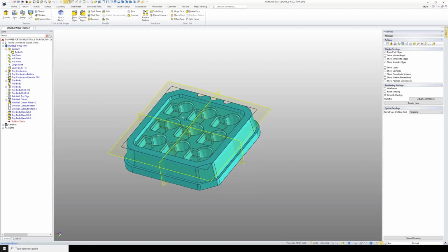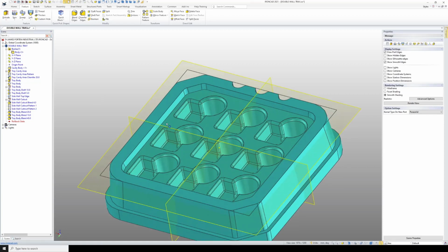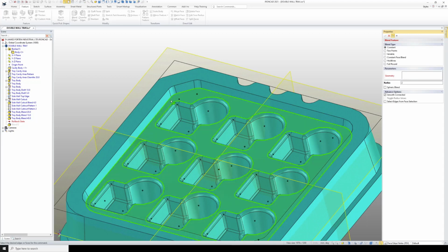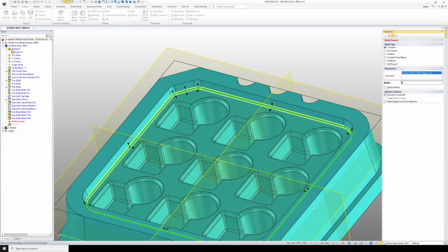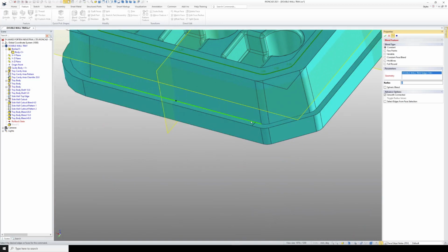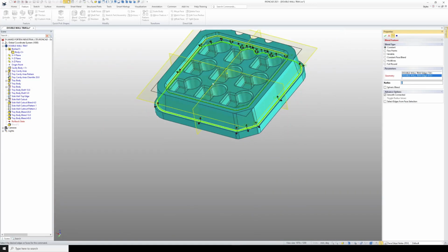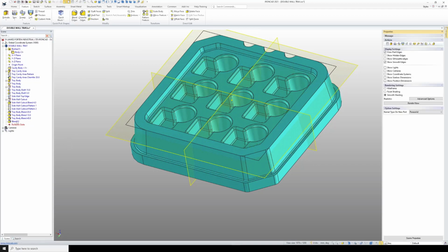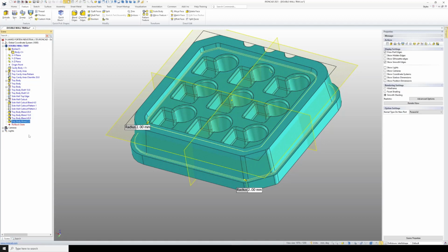And now we want a 2mm blend on the inside bottom there and on the outside. So blend 2, and because these are all tangent, that's going to just require the one click, and the same with here. So the order in which you do the blends is important, just to minimize the amount of clicking. So I tried to make sure that I had tangent results. So that's that one. And again, that was 2mm.